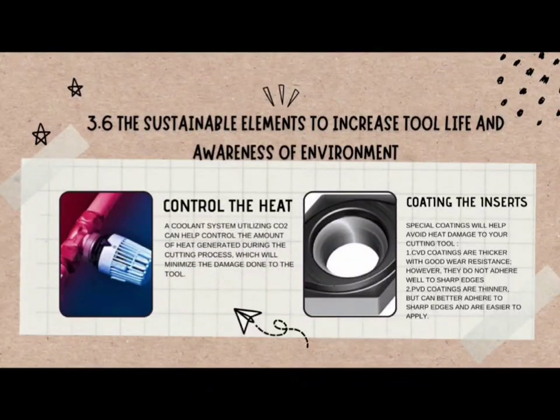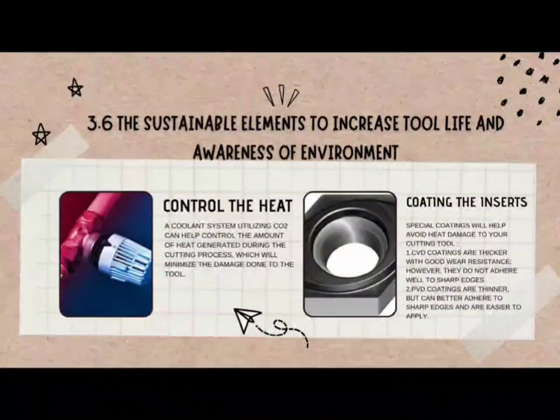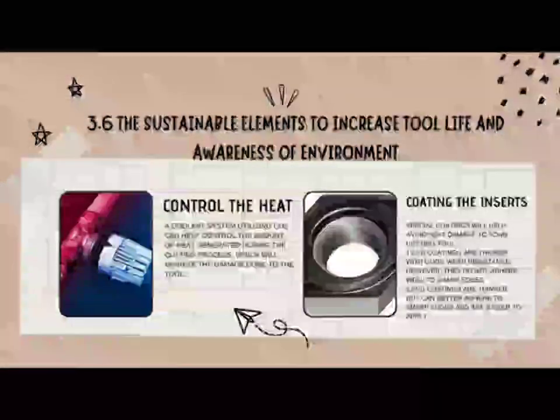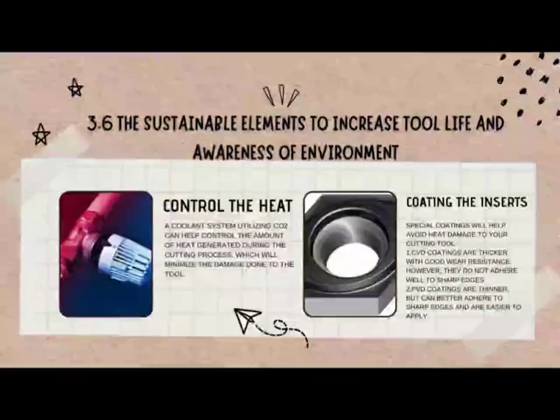Secondly, coating the inserts. Special coating will help avoid heat damage to your cutting tools. Firstly, CVD coatings are thicker with good wear resistance, however they do not adhere well to sharp edges. Secondly, PVD coatings are thinner but can better adhere to sharp edges and are easier to apply.